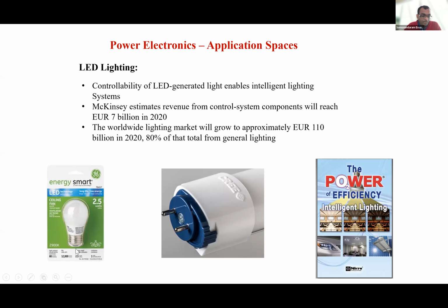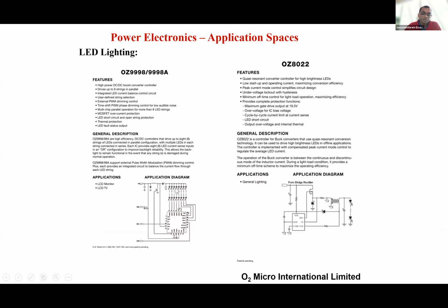This guy, on the other hand, you apply the same AC voltage, and inside of it there is a lot of miniaturization happening. This picture is a good picture. In this little cylinder portion is where you have all the rectification happening, the control happens there, and the driving of the current through the LEDs also happens here. Because of this, it's a very highly efficient system.